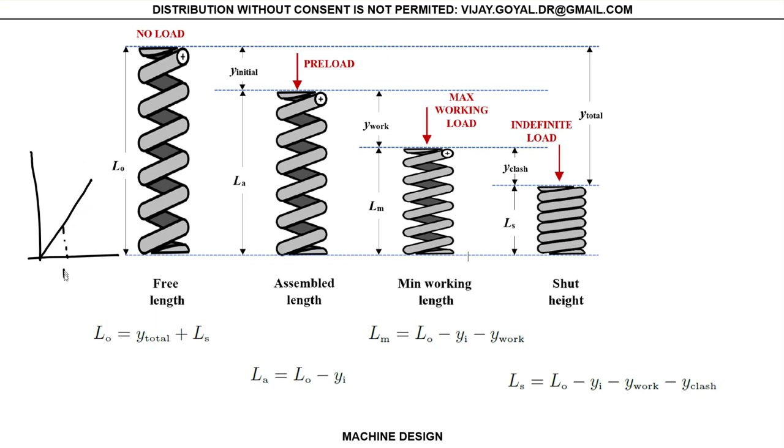So if I'm saying I have y initial, that's also going to be related to some F minimum or F initial, and we have a slope k. This is load, and this is your displacement. So this is known in the problem. These curves are typically known from the problem for every spring, and they come from test data.